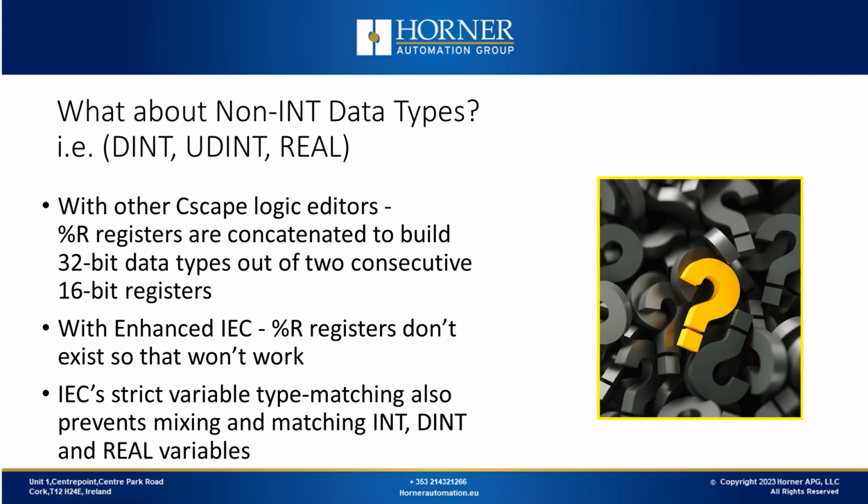Now we'll look at non-integer data types. Traditionally, manufacturers have exchanged floating point data, double integer data, and more through Modbus, which is based on integer data. In the register-based, variable-based, and standard IEC editors from Horner, there was a conventional register-based structure for easy concatenation of 16-bit registers into real and floating point data. However, with Enhanced IEC, this shortcut isn't available.